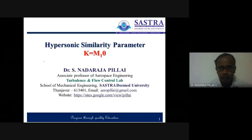Later, when compressible flow exists, we call the Mach number. M infinity is a ratio between V infinity and A infinity, where A infinity is the velocity of sound. So it goes like that. We are always very much interested in showing the non-dimensionalized number so that it can be used anywhere, in any of the literature and any of the research. So today our topic is the hypersonic similarity parameter.